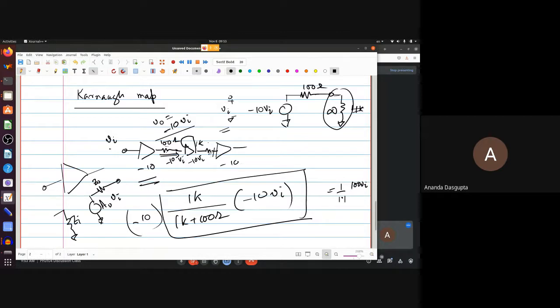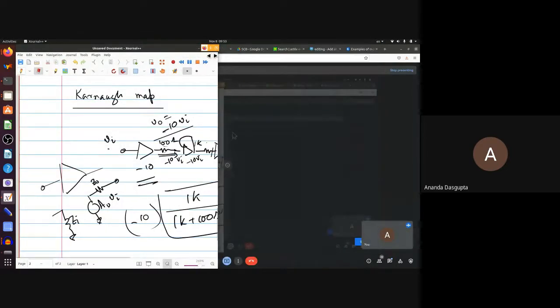But then, as far as the next stage is concerned, the unity gain buffer is actually the source for the next stage. And there the output impedance is very, very tiny. So almost no drop occurs, despite the fact that the current can be substantial. You have a 1K input impedance of the last stage, so it's going to draw current. But because the output impedance of the unity gain buffer is so small, in the input stage it looks like 100 ohms gets connected across infinity. In the output stage, that is for this one, it looks like you are connecting a 1K resistance.